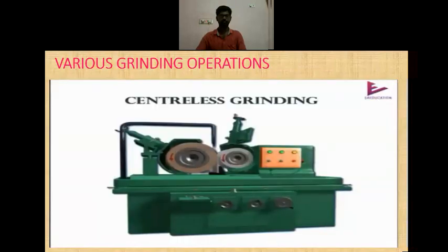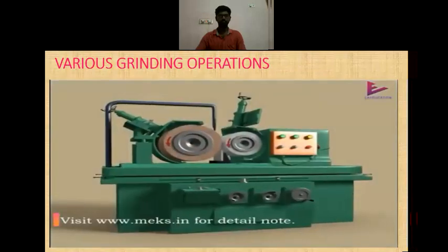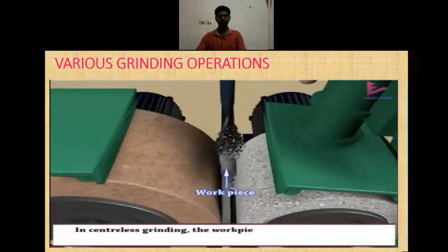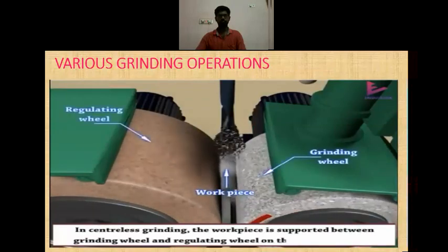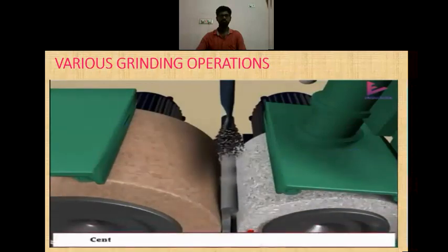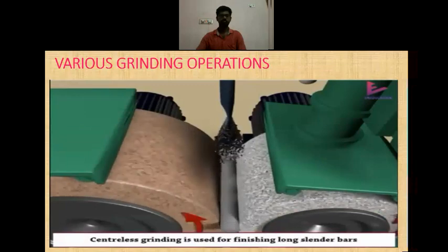Centerless grinding. In centerless grinding, the workpiece is supported between the grinding wheel and regulating wheel on the work rest table. Centerless grinding is used for finishing long slender bars.